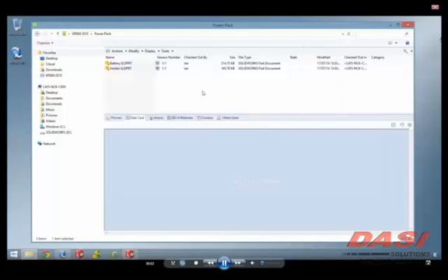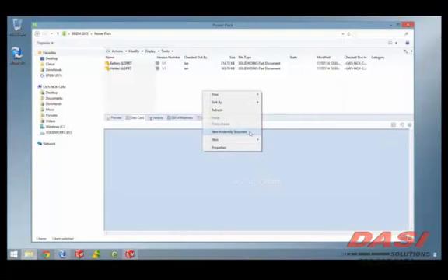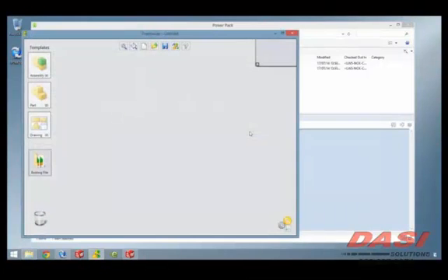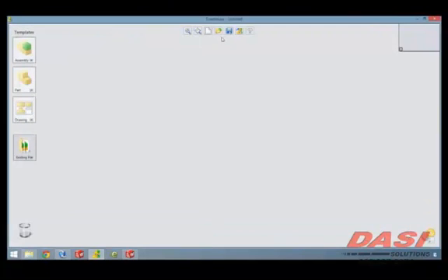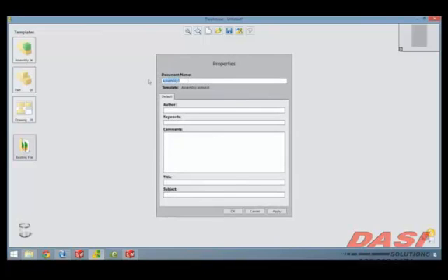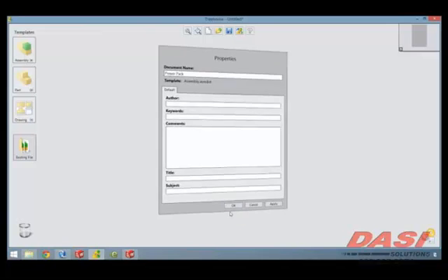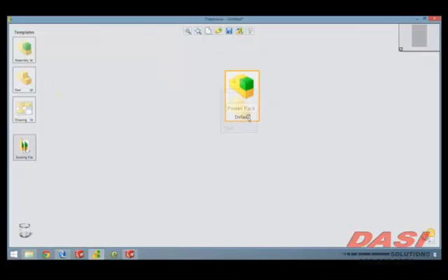So when we've got these product structures predefined, what we can do is actually use this new tool. It's actually an old tool. It's part of our SolidWorks Labs capabilities, but it's a new tool called Treehouse. Treehouse allows us to go ahead and predefine by dragging assemblies and parts and structuring them together. Now these are based on property templates, so the properties are the same as they would be as you're starting a brand new SolidWorks file.